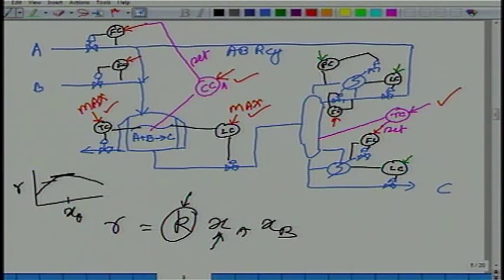So when you said XA is to be 40%, then you are assuming there are only A and B. Well, yes, that is true. So maybe what we should be doing is C-free basis. Maybe we will control this composition. This will be only A and B, with very little C. Now this can be made 45% probably. This will work, some composition inside the recycle loop.